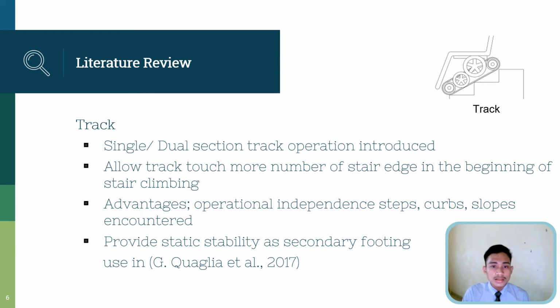This states that the benefit of this strategy is that it allows the vehicle to begin and finish the stair climb in such a way that it makes contact with a more significant number of stair edges or surfaces and avoids instability. The advantages of this method are the operational independence from steps, curbs, and slopes encountered. Moreover, the track-based concept also provides static stability and prevents the wheelchair from overturning, in Gigoglia 2017.